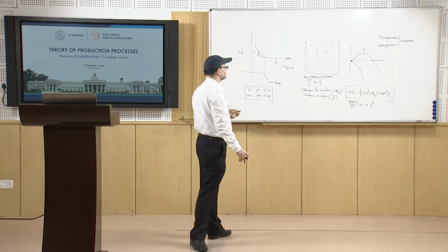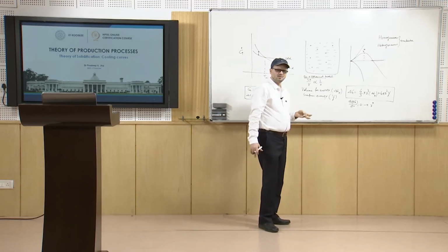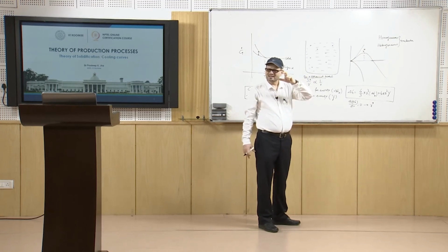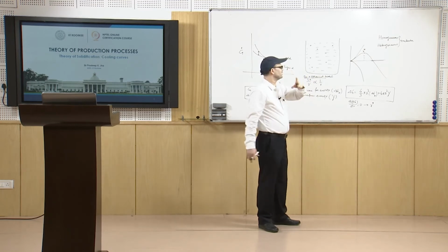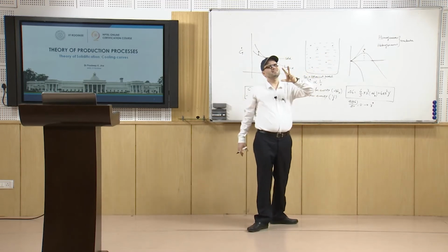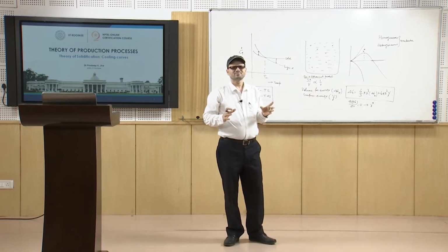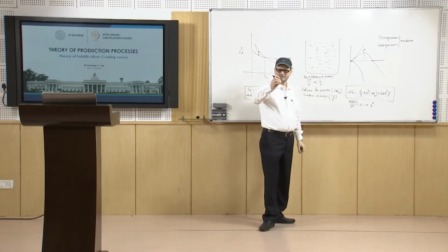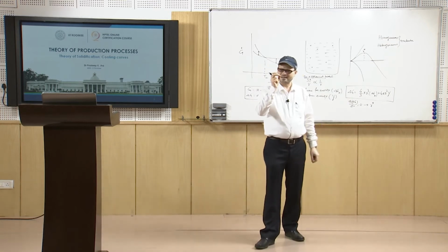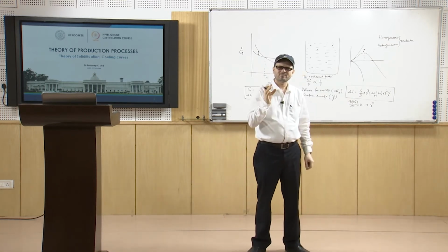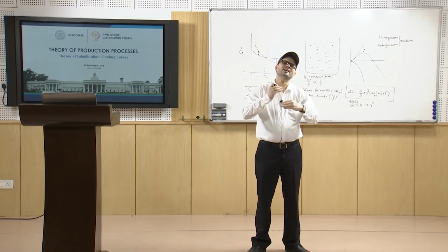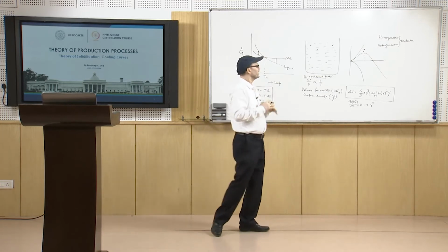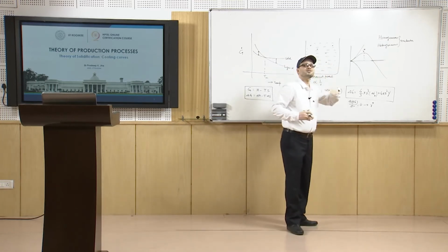As we discussed, for nucleation to occur you have two conditions. One is the favorable condition because of the volume free energy term, and because of the creation of the extra surface, you have a condition which is basically retarding. Now, if you have any foreign particle available which gives extra surface, nucleation gets some help or support from where it starts.